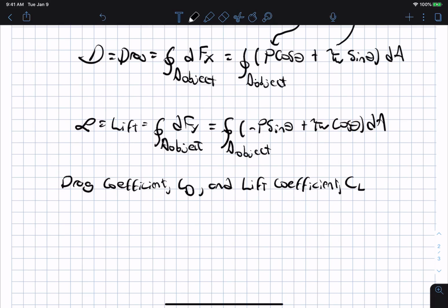Okay, and the drag coefficient is defined as the drag force over 1/2 rho times the free stream velocity squared times A. And I'll define what A is later on, because it is different for different scenarios. You need to be careful of that if you look up drag coefficients in tables and things like that. You need to be very careful how A is defined.